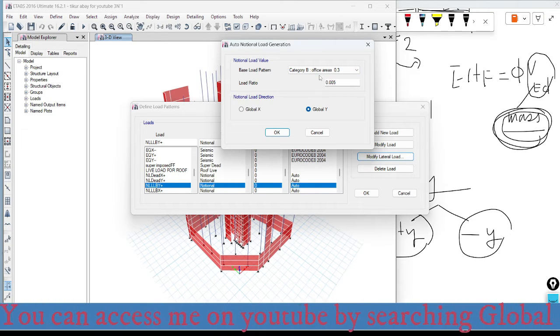So as we have already defined the live load of the floors, which is categorized under category B, which is office building, for office building we can use the phi value, that is the live load reduction factor phi 2, which is 0.3.